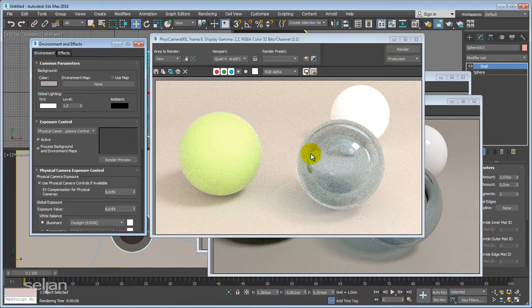Now there is no problem at all. We can quickly fix this by using the exposure control. So I'm rendering a preview that will actually create the same render in small. Now it's an interactive render, so I have the luxury to come in, and the exposure value, if it's lowered, I'm using the drag.